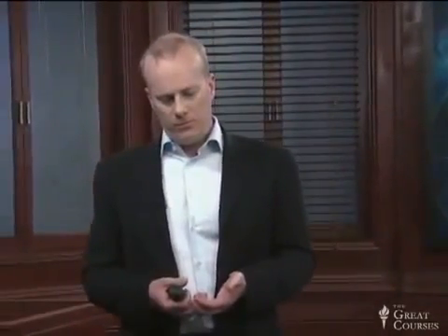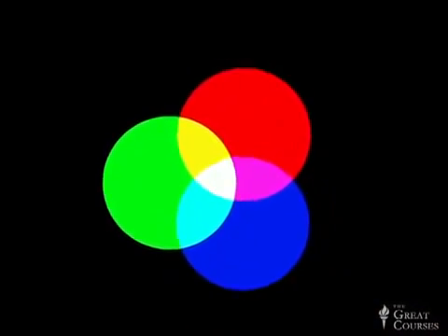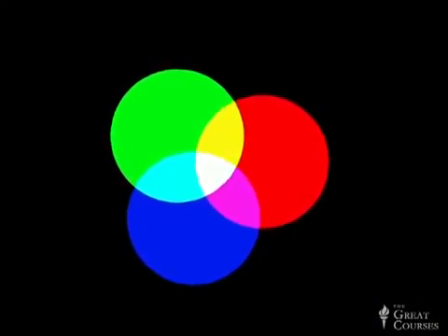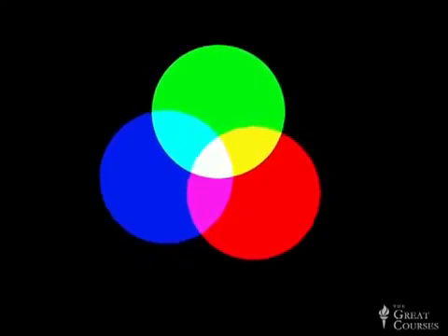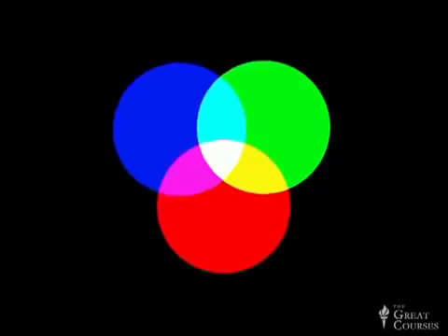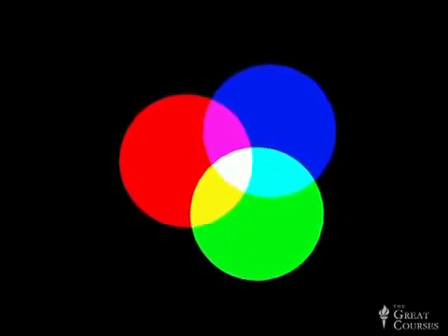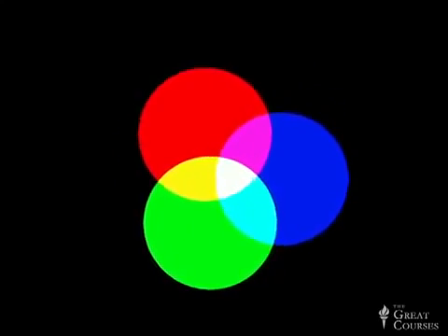Now, you may have been wondering a bit about how we see color at all in today's digital image sensors. And the answer is that at the moment, we put little arrays of optical filters on top. You can probably picture a color wheel in which we have a red and a green and a blue filter that can transmit those corresponding colors of light from behind a white light source. And those color wheels seek to map onto our own eyes' sensitivity, where we have our color sensing also based on different sensors in our eyes that are differently attuned to the red and the green and the blue.